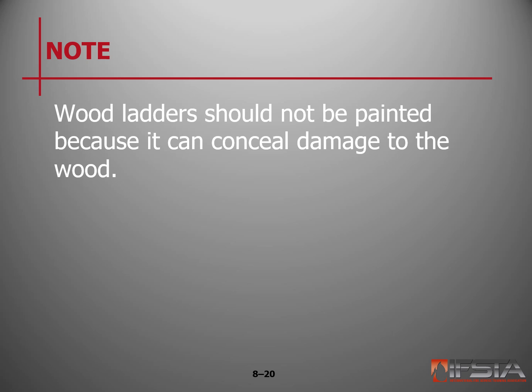Something to note here, again: wood ladders should not be painted, because this would conceal damage to the wood. With a wooden ladder, the wood needs to be protected with a clear type finish. That enables us to see if there's any dry rotting, to see if there's any cracking of the wood, those kinds of defects that oftentimes paint will cover up.